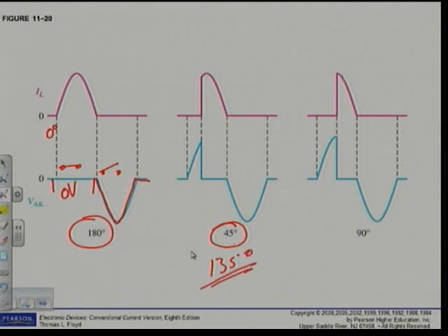That means the best way to rectify the problem in your books, write down, if you look at the question, relation to the load current for 180 degrees, then it shouldn't be 45 degrees. It should be 135 degrees. That means here we got conduction for 135 degrees. The question in the book is wrong. Change it, rectify it to 135 degrees, please. It's not 45 degrees, it's 135 degrees conduction, alright?